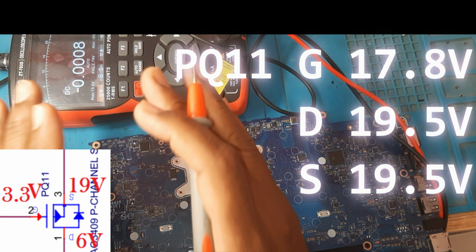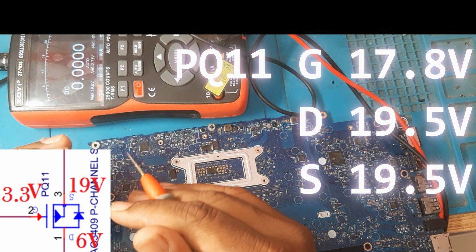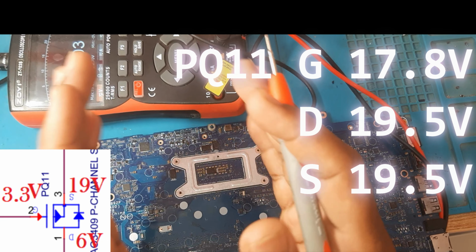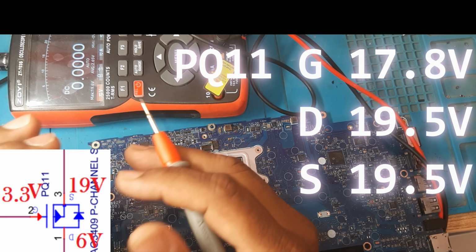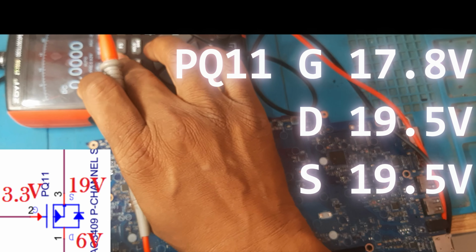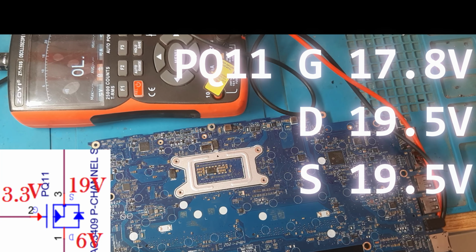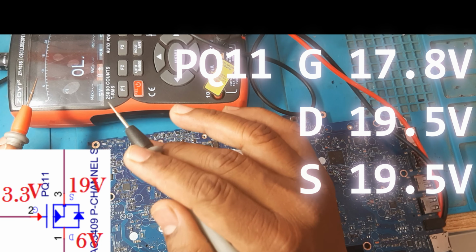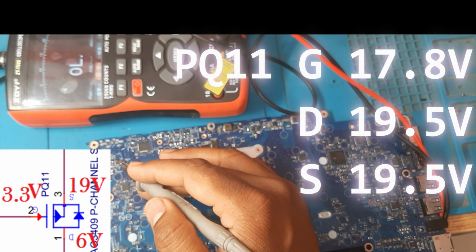All the components, first preference goes to checking the schematic one by one. All the protection IC logic will be there, no, that circuit. In a cold test only you need to check. Cold test means you need to check using the beep sound. Okay, now I had some doubt, correct? Here the source is the same and the drain is also the same.